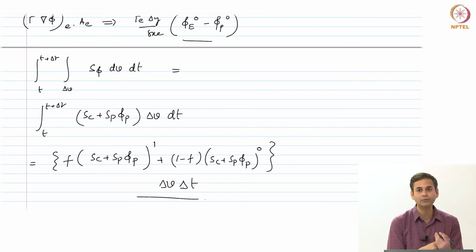But if you do it that way, or in either case, you have to specify how you chose the time discretization, okay. What is the f value you have used for diffusion, for source terms and for the convection term has to be specified when you solve any problem. Many a time it is probably required that you choose different f for different terms in the equation, okay. That means you are kind of controlling what factors would come into the equations.